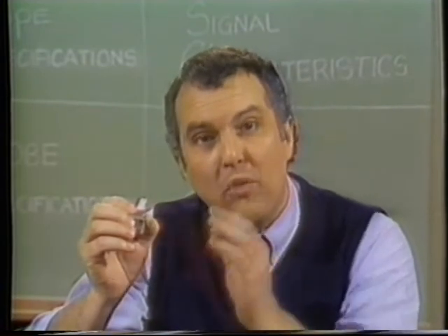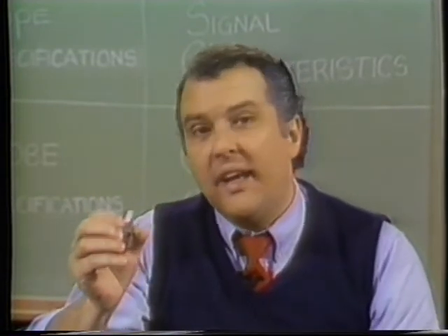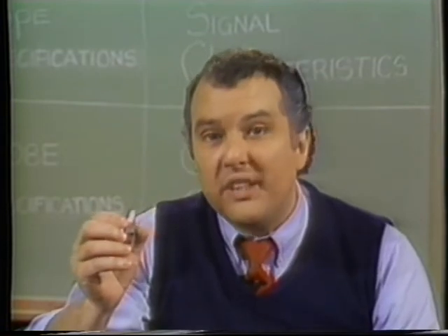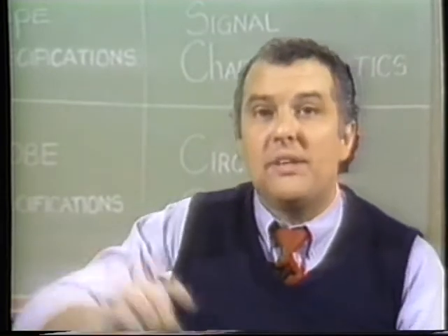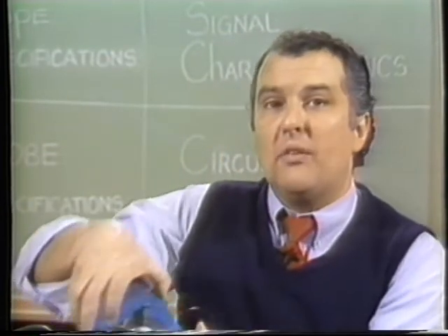It has an exceedingly small replaceable tip for probing tiny components. It has the high Rin and low Cin required for high performance. Actual input impedance is 1 megohm, shunted by 1.8 pF. Bandwidth is more than 750 megahertz. It's designed to be mounted on a probe card for use in automated test systems.